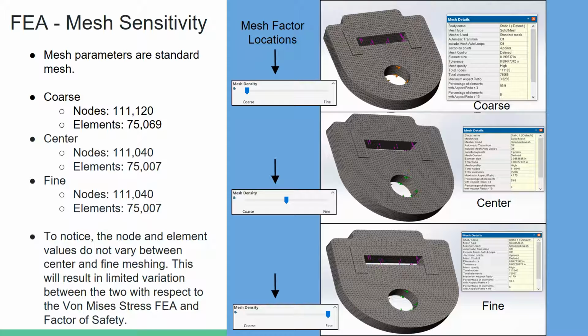The greater the number of elements we have, the more accurate the stress distribution in our buckle. The variation between each meshing possibility was relatively low, which is good for analysis. This good state of sensitivity of the buckle may be the result of the mass of our prototype. However, if we reduce the mass, the negative payoff would be non-uniform meshing capabilities. This was one of the design factors we took into consideration.